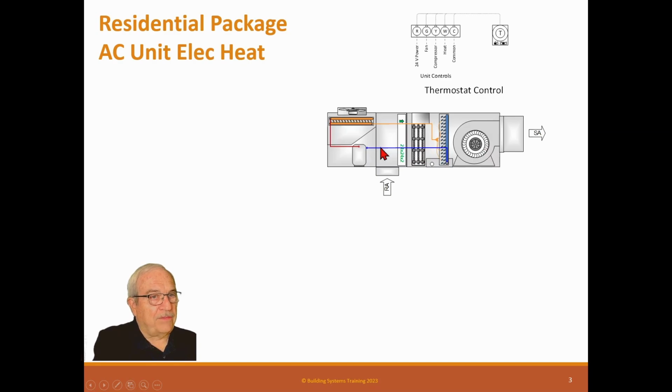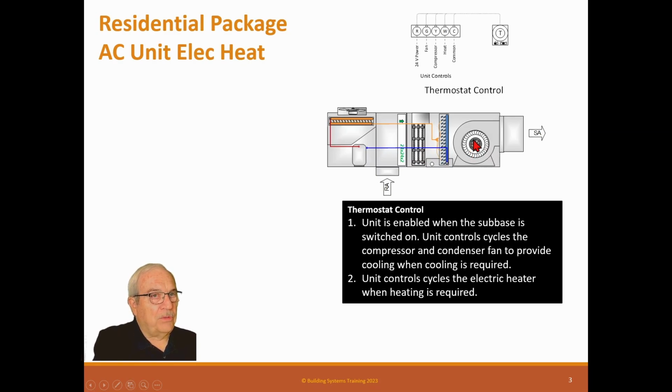Okay, so now if we have this in a commercial system and we want to use it differently, we'll show you how you put a DDC system on this. Now these sequences, this actually is a sequence of a thermostat. All these sequences I'm going to review for you today are just high-level sequences intended to explain what the unit does. These are similar to what an engineer would put on the drawings. These are not programmer sequences. They don't include timers. They don't include any reset outs. They don't include any exit points. So they're not really intended for a programmer.